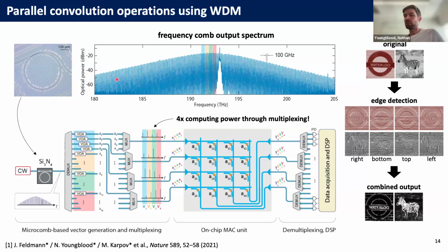But I think primarily in the wavelength range that we're talking about, it's limited by those directional couplers. So that's kind of the first thing that would be a limitation. What would be interesting and hasn't really been explored that much is if you take a source that is not a great coherent source, right? So let's say that you have an input source that is broadband, for example, a superluminescent LED or spontaneous ASE source, and you filter with a bandwidth that's, let's say that you have these bands, but they're 100 gigahertz in spectral width.